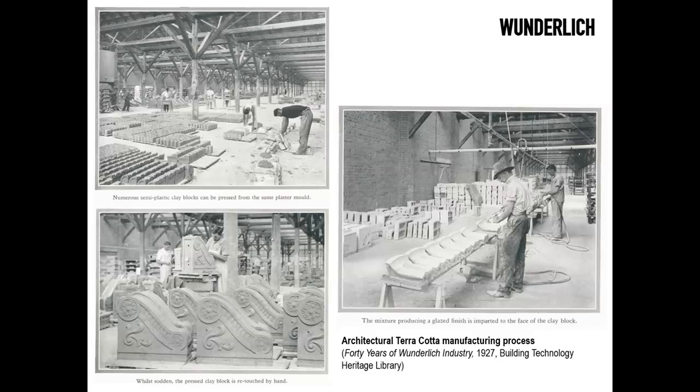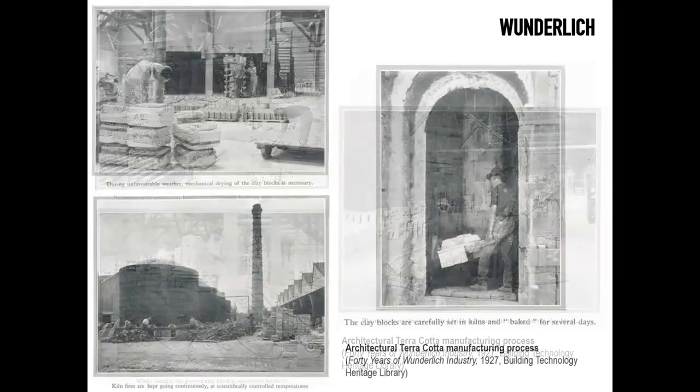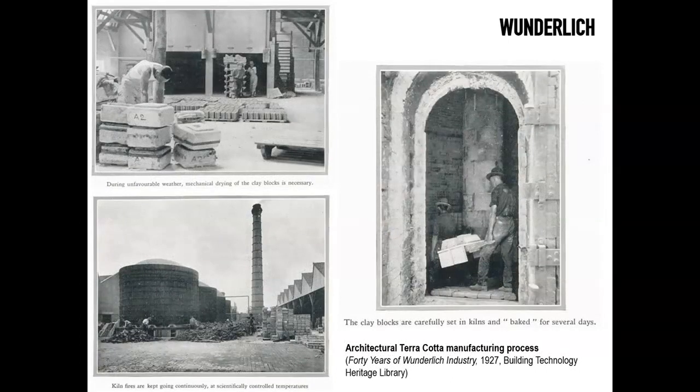Then after the fresh clay is pressed or molded into the final product, there will sometimes be a stage of retouching to bring some more consistency or eliminate imperfections of the molding process. After that, the terracotta products will be glazed so that they can be enameled, basically to have a long-lasting finish, so that it does not expose the material to freeze and thaw or collection of dirt, or also absorption of moisture that then can create further problems down the track.